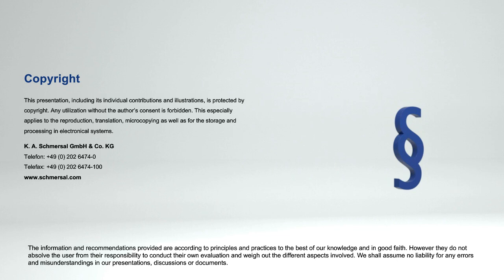And I wanted to clarify that because I believe, and if I misunderstood, let me know, that when you said is it the overall of the machine? What we used to look at, before the statistical data really got a lot of weight when it came to ISO 13849 and IEC 62061, so PL and SIL, we were claiming categories for a machine. Hey, this machine is control category 3. Well, with these latest standards, we're not looking at a machine as an overall safety function. We're looking at the individual safety functions.